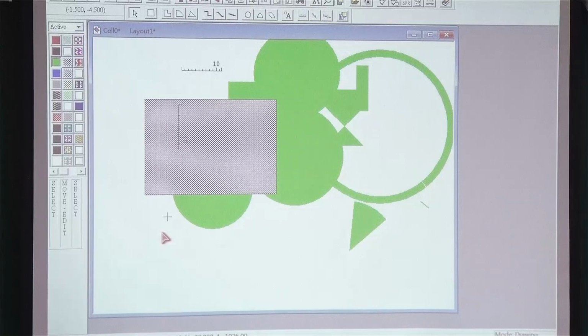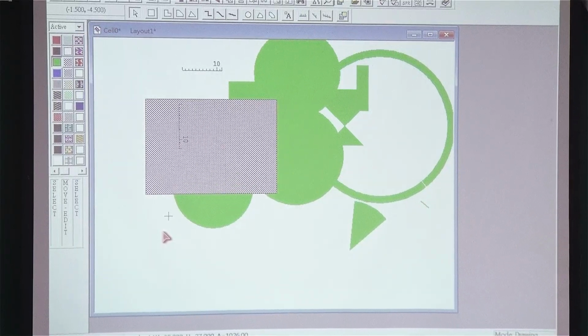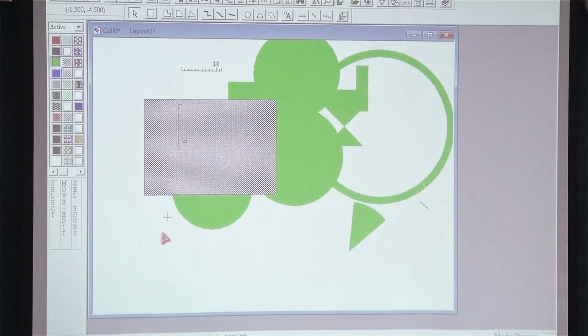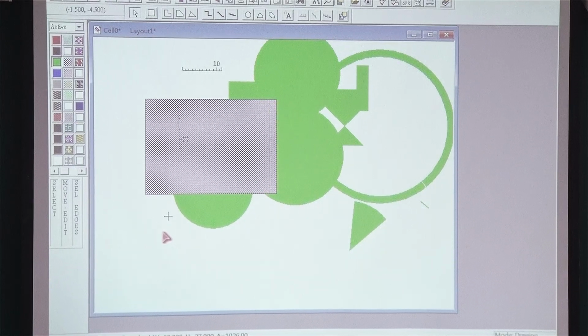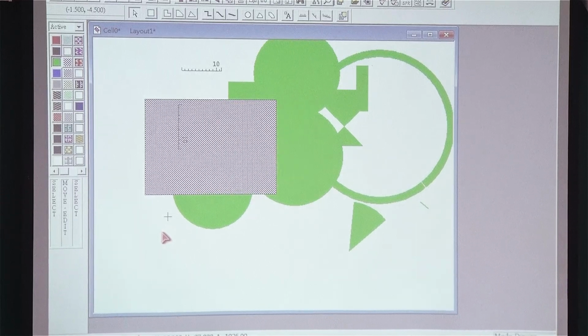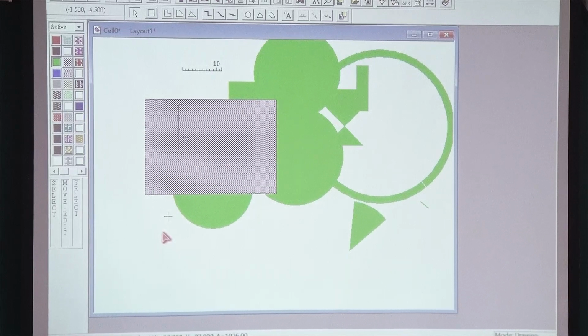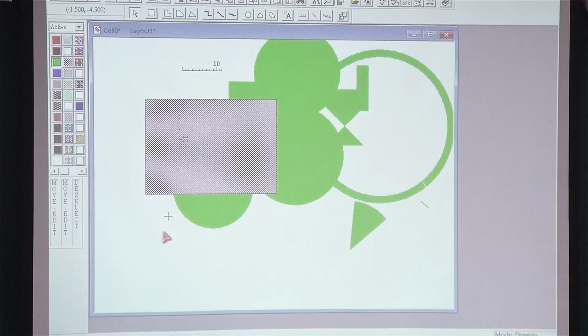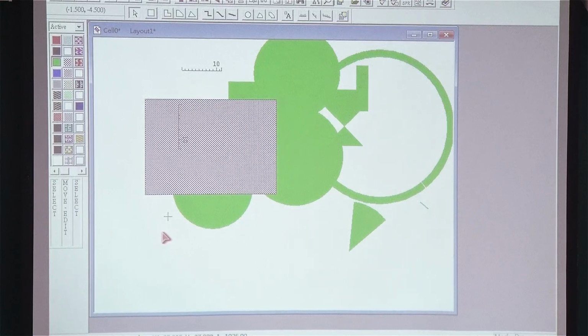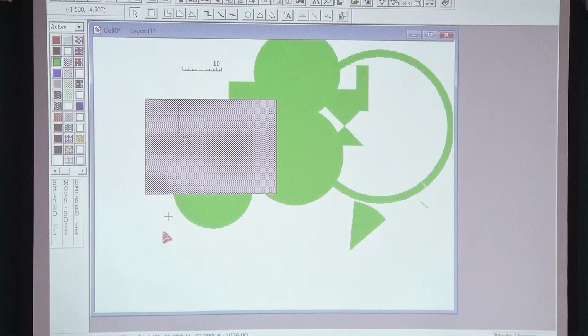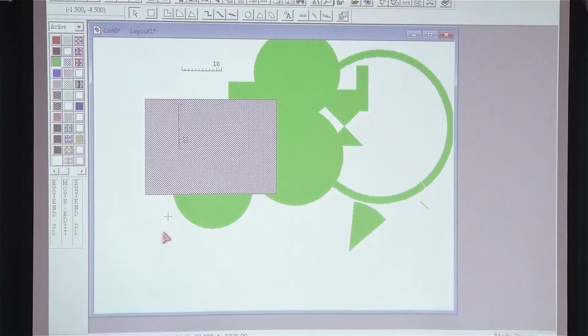So the mouse operation is not only for these 3, okay? You can click on the control, you can see the change. When I push control, you can see the function change for the mouse. For example, the original select right button now becomes select edges. You can do an edge selection. If I push on the auto, everything changes. You can move. You can deselect. If I push on the shift, you can change into the extended selection, move, edit, or extension